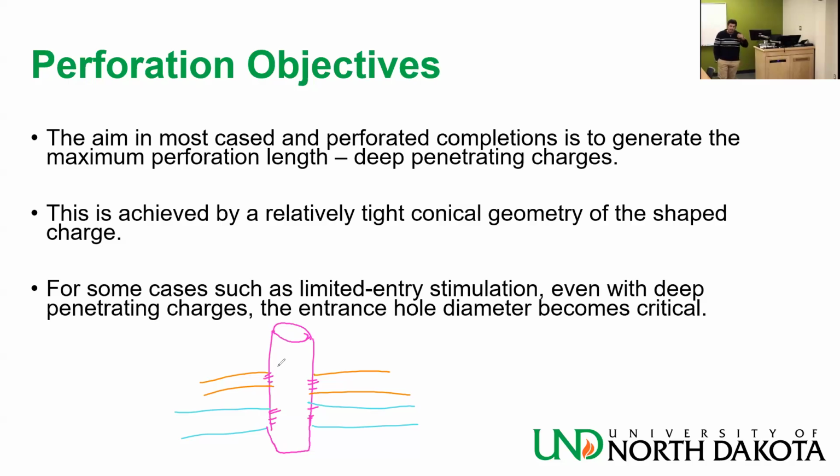Now for stimulation, limited entry design nowadays is so that no fracture perforation cluster is left without fluid. You don't want a situation where all the fluid goes to the same perforations and generates one gigantic fracture that keeps growing and growing and growing. Whereas if you had a limited entry technique in place and properly working, it will even the distribution of fluid throughout those perforations.